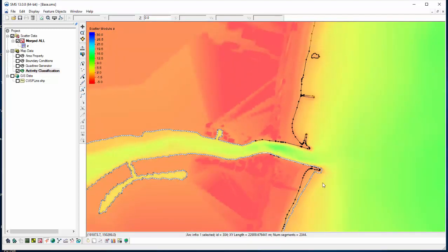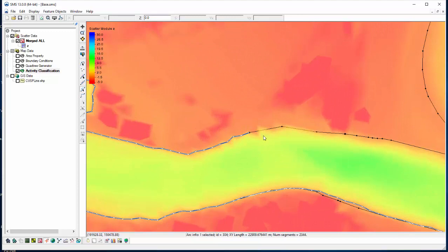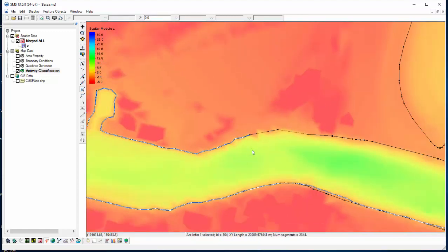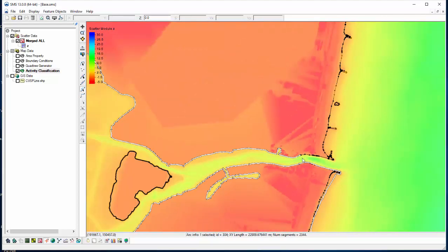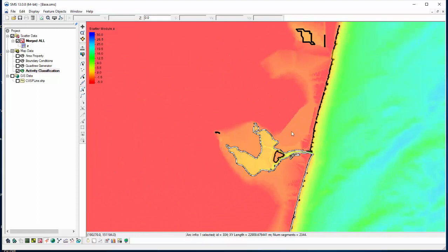We would just keep doing that and move it from one place, removing the extras, and then making sure all of these arcs are connected together, as I just did with that create arc. It doesn't matter that they're separate arcs, but what in the end we want is one big polygon that defines our area that we can use to say everything outside of this area is land.